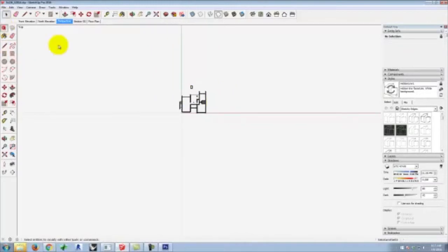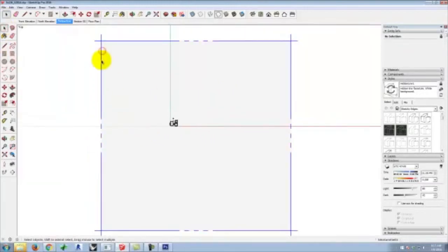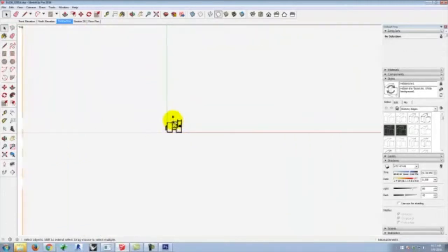Now, we used to have a tool where we could select the section plane and then right-click on it, and there would be a plug-in that said Add Section Cut Face, which fills in what we've cut through. When they upgraded to 2016, that wasn't installed, so I don't have a way of doing it. At least on my machine, it doesn't work. If you guys right-click and see it, you're more than welcome to try it. But for me, we're going to have to pass on it, do the post-processing of it in Photoshop rather than do it with the actual section cut face plug-in.